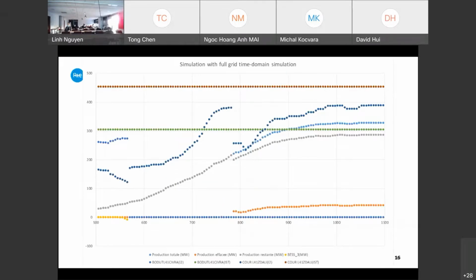So this is an example. Here we have a line coming. This is the small one I showed you, and this is the limit, which is low here, 300 amperes only. And at that time, the software, the optimizer, decided to switch off. So this line comes here, and here we have another line. When there is a switch off of the first line, the current increases, but this is normal. And then the wind makes it increase here. And this is the maximum of these lines.